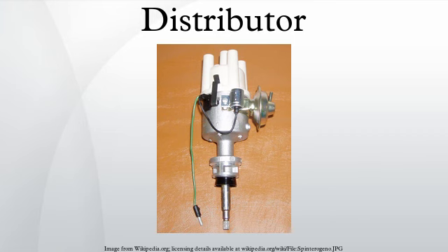4-stroke 4-cylinder engines can be built without a distributor, as in the Citroën ID19. Two coils are used with one coil firing two of the spark plugs simultaneously, resulting in a wasted spark on the cylinder currently on its exhaust stroke, and the other coil used for the other two cylinders. This system has been scaled up to engines with virtually an unlimited number of cylinders.